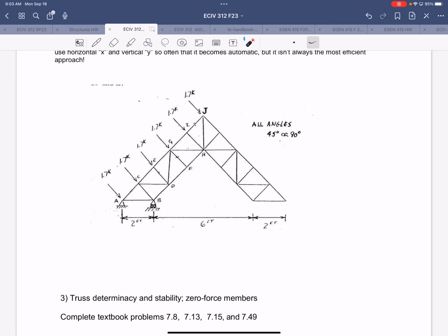So using method of sections, you don't have to make cuts that are straight lines or anything like that, right? You can make cuts that isolate joints. So you can cherry pick joints out of the truss and analyze the ones that you want, right? So keep that in mind. That can be helpful as well.